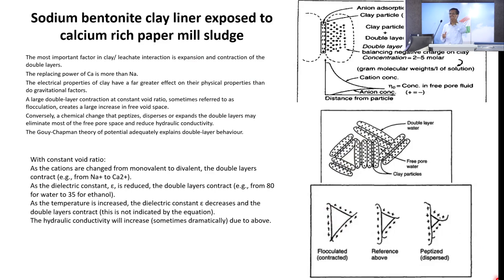So that's why, when somebody was asking, I said these aspects come into play. If you have bentonite in that composite clay liner, is it reacting? If it is reacting, then there will be swelling. And then what I was talking about, Darcy's law validity and invalidity. So these are the cases where you have to be careful when you want to use such cases.